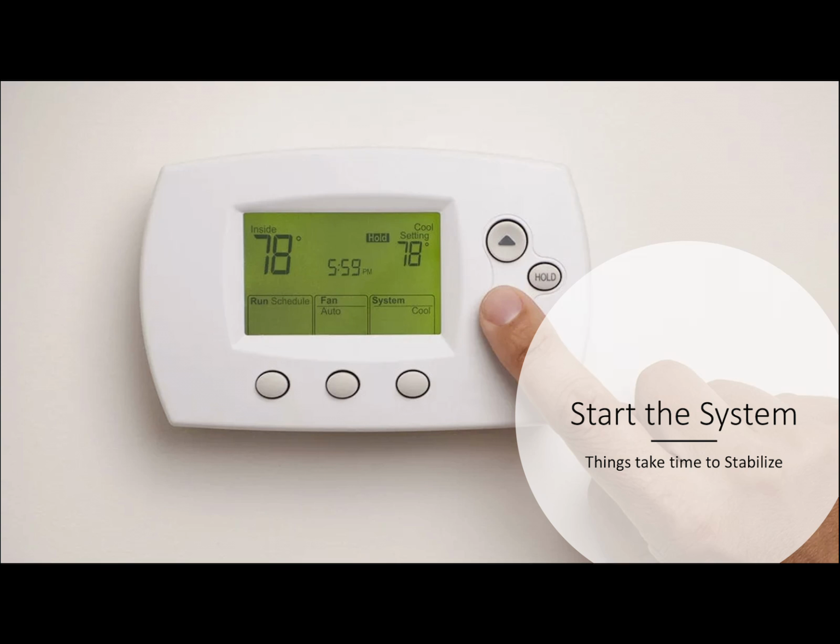Typically, it takes 10 to 15 minutes for an air conditioner to get to its full capacity. So you've got to give it a little bit of time. And measureQuick actually has algorithms that'll tell you when the system's stable. So we've got our app downloaded, got our tools mapped, all that kind of stuff's done. It's a one and done thing. We've got our probes deployed where they're going to go, and now we're going to start the system and let it run.